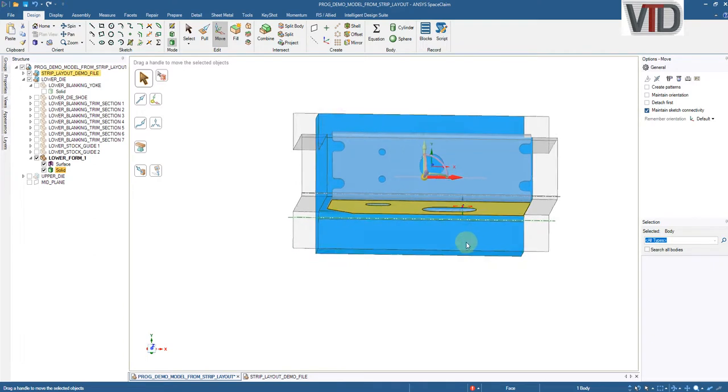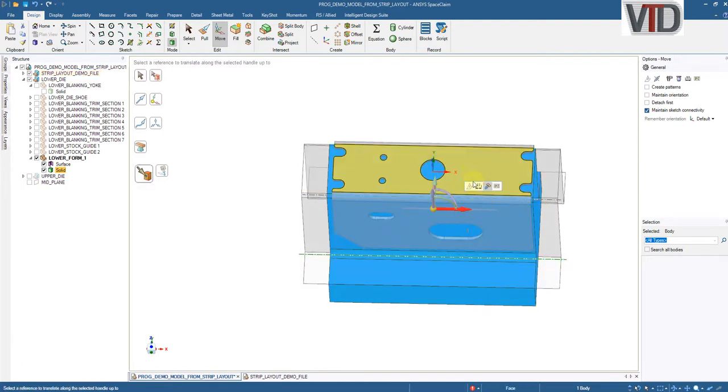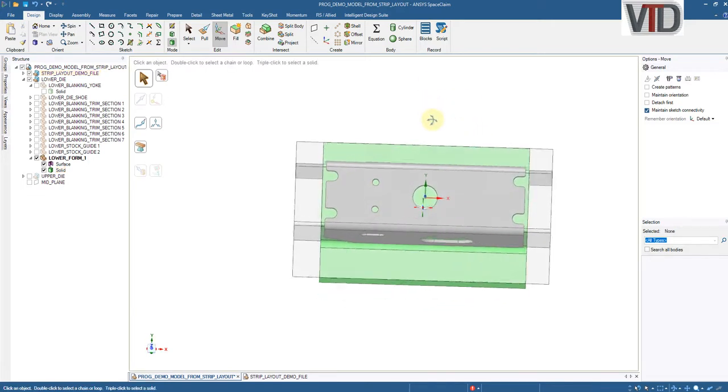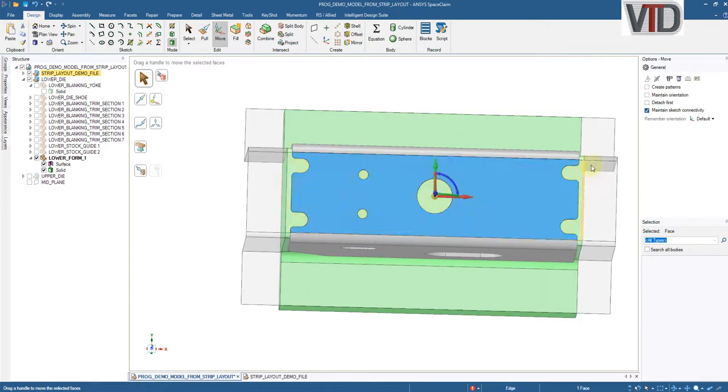Now, the silhouette of the part surface is safely going to be a square as well. So I'm going to do up to, and I'm going to pick the top surface of the part. It's going to find the center middle of that surface, and it's going to line up to it. There, you see that? So now I'm dead center in the X to the part data, because I see that the surface that I picked goes in the extent to the end of the part.